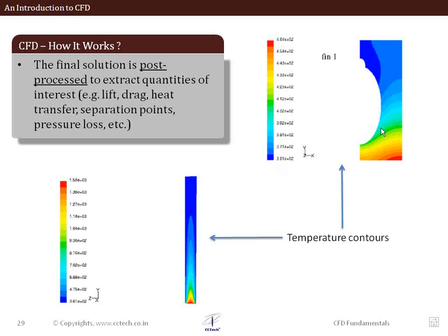Now if we analyze it from this view, from the view between the fins, you can see the fluid is moving further, and the temperature is also varying accordingly. So we have the temperatures varying in this area, and we have areas where the temperatures are quite high, which is typically encountered for flue gases, and reducing as it moves into the domain.